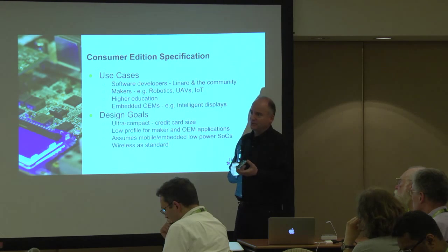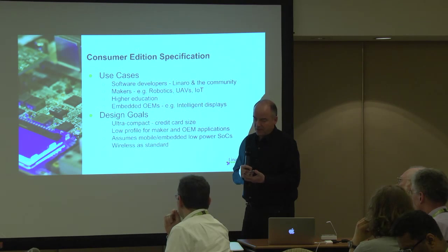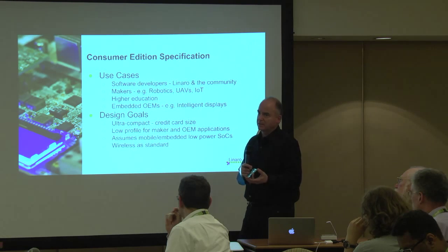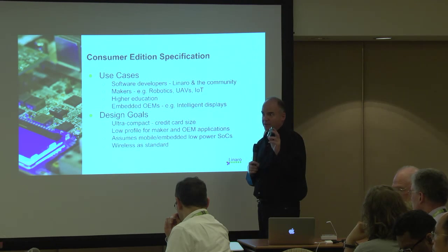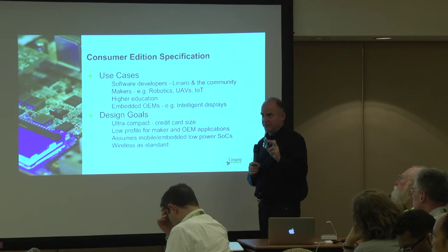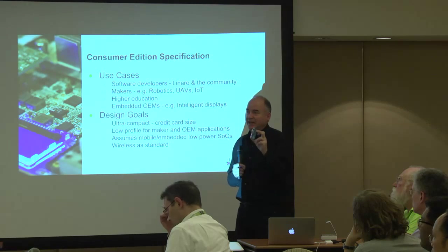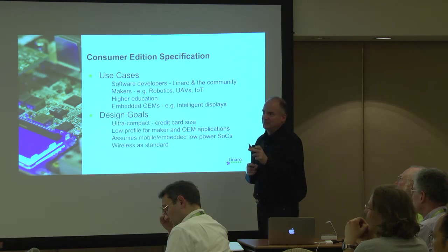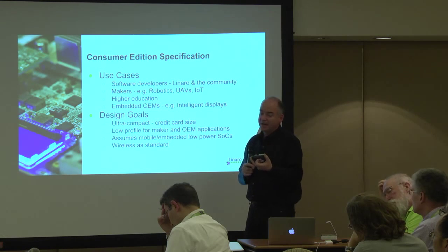You're starting to use board real estate to implement the actual functionality. On the other hand, an SoC for the digital TV market, I know one company designing a board that already has HDMI directly on their SoC that puts out 4K video. They're actually going to have quite a bit more space because they haven't got to have the DSI to HDMI bridge, and they can use that for something else.